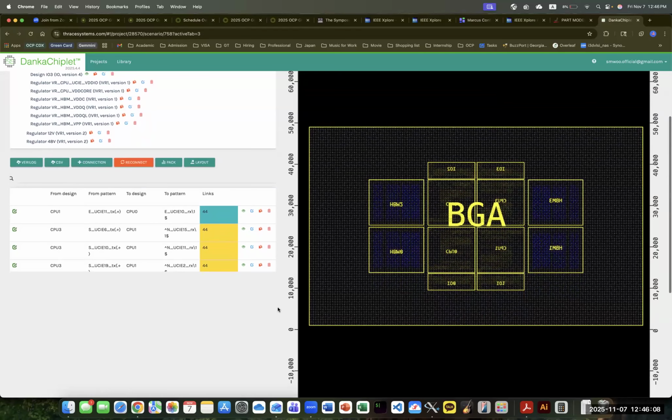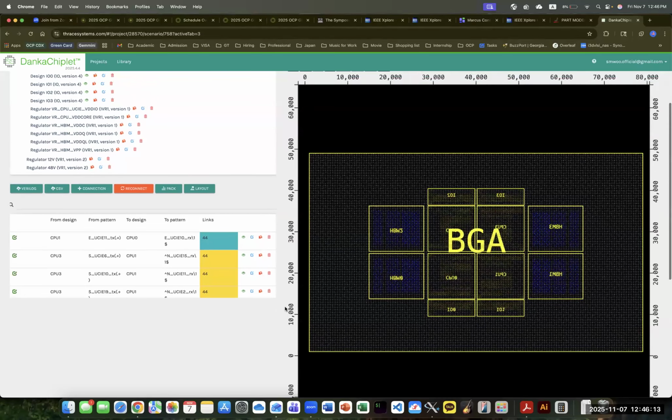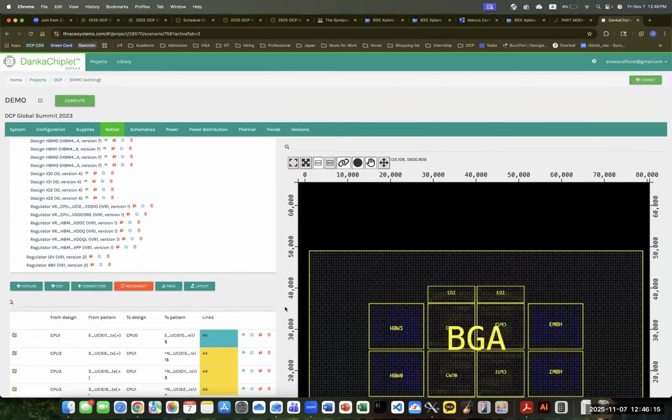Yep. That's exactly what Marcin mentioned, the bump map. The next immediate task is to get that IVR set up and place it somewhere and see how it looks. Right. We'll size the number of IVRs, add them to the floor plan, and see how things look. So I guess we would have C4 bumps on the VRM. Yep.